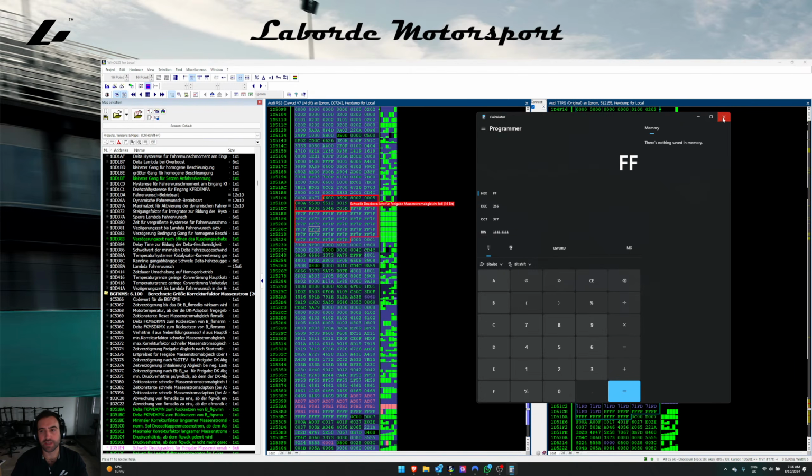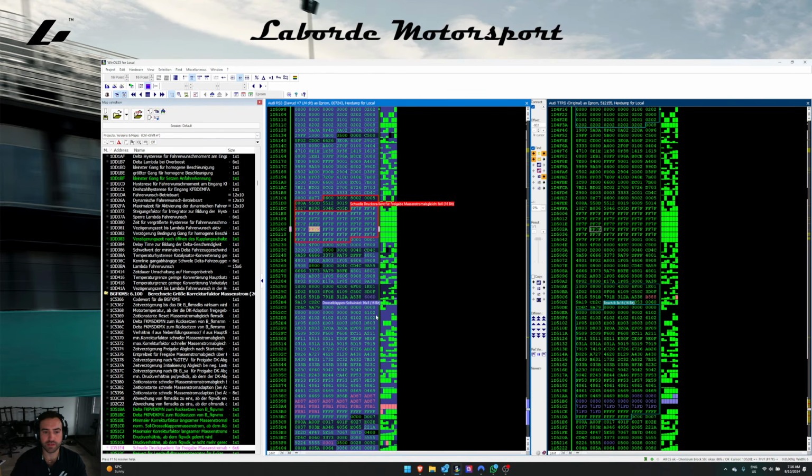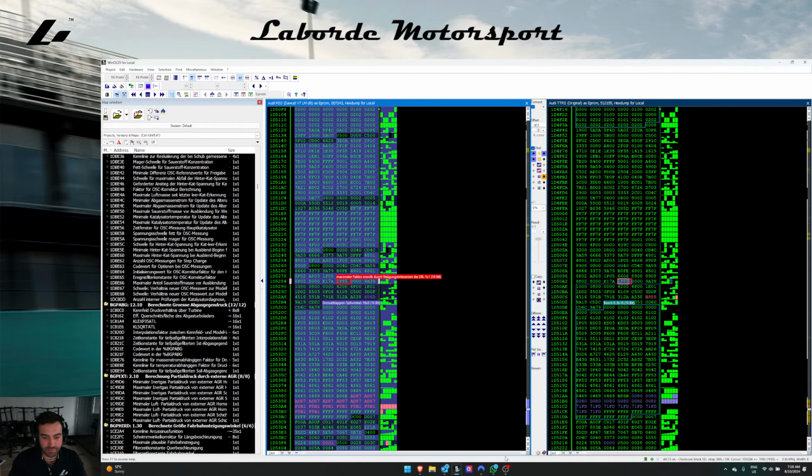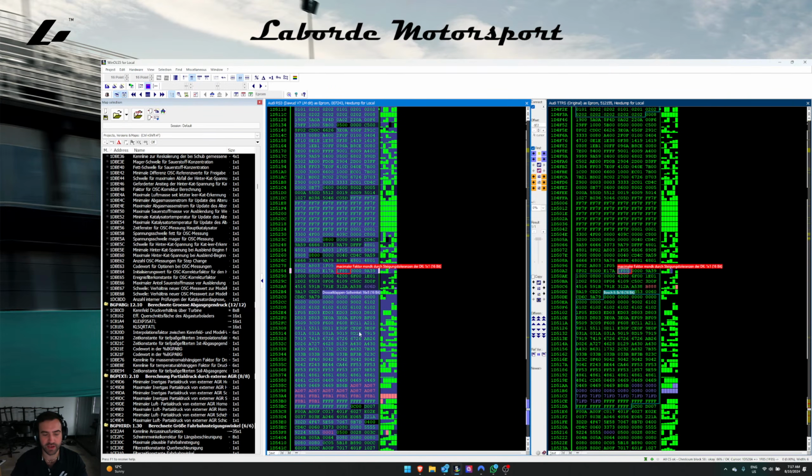So we pretty much have to turn off some of the monitoring systems that will allow it to go over that sort of boost pressure. First of all, there are some ratio factors for the monitoring of boost pressure. We need to limit those and disable those in order to achieve that level of boost pressure on this car.